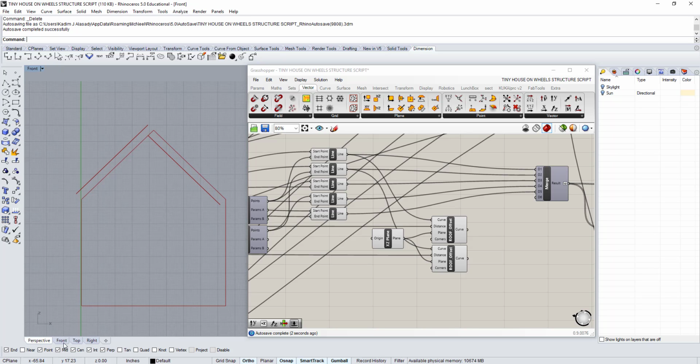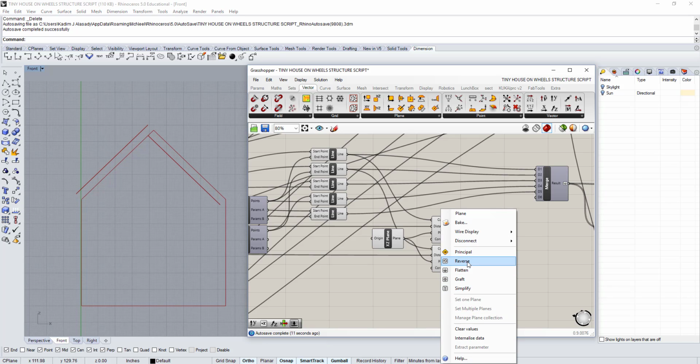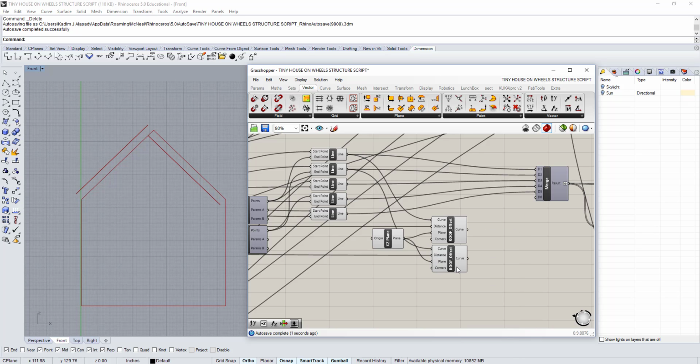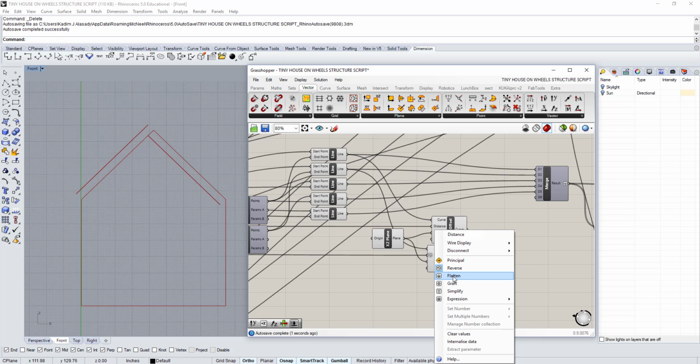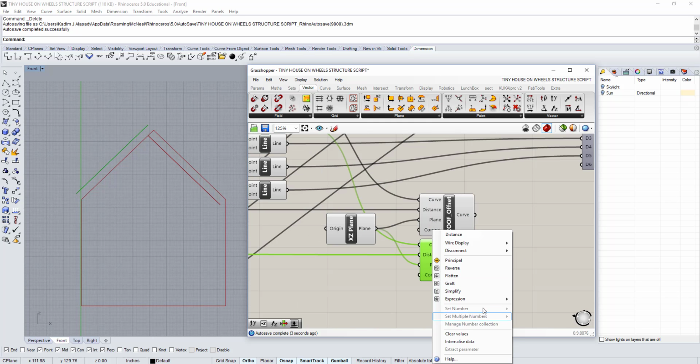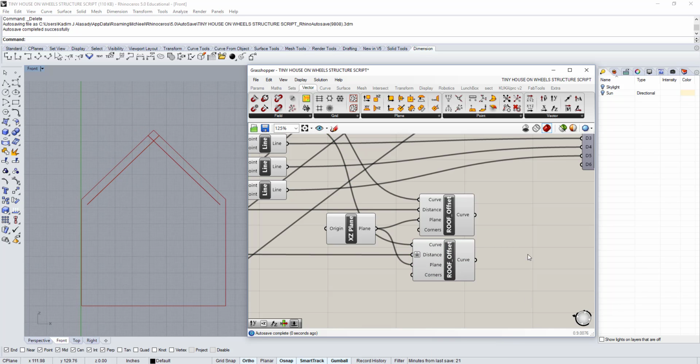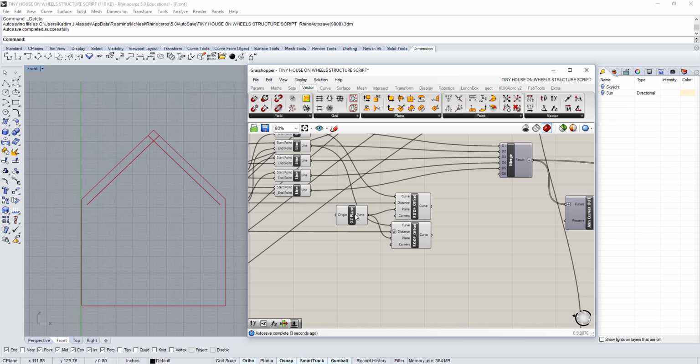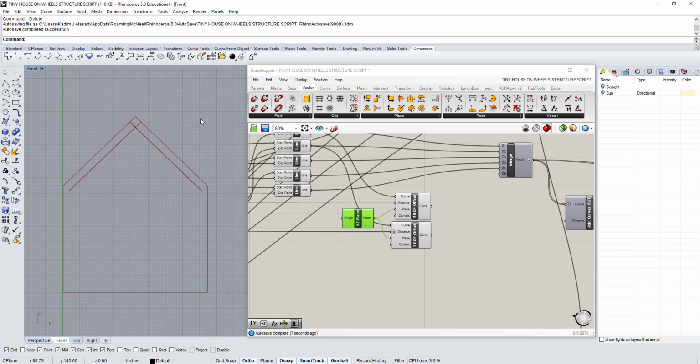And you see that's also another problem there, it's offsetting in the wrong direction. So maybe what happens if we just reverse this? I'm sorry, not that one. Let's reverse this one. No. So let's type in an expression and do -x, commit. There it is. Okay, so we offset these in the correct direction, on the correct plane.